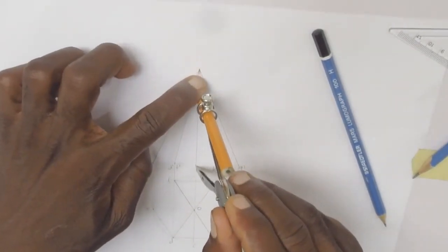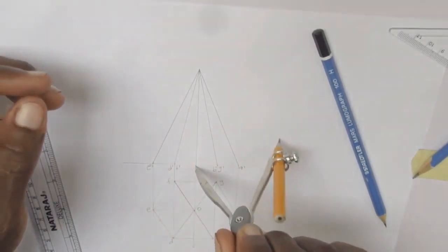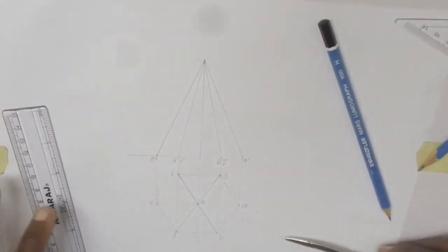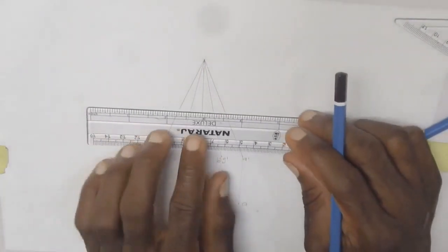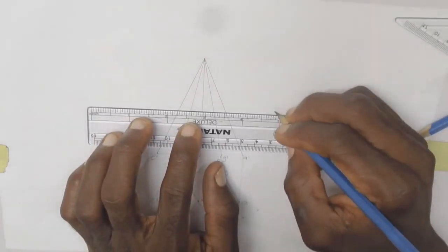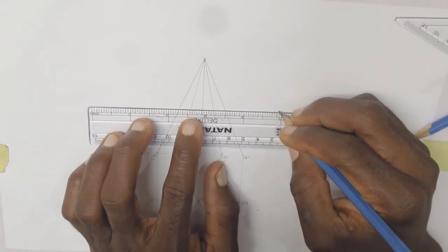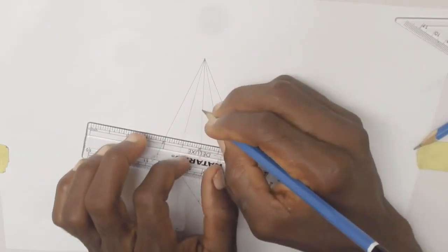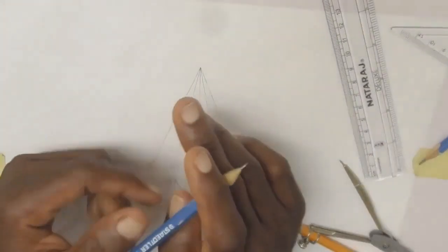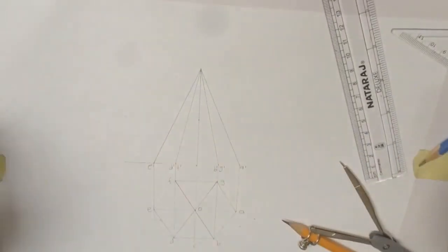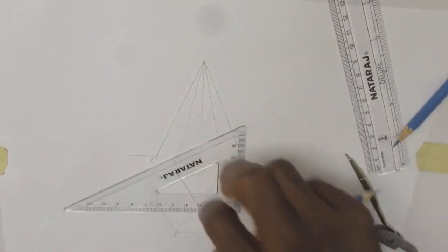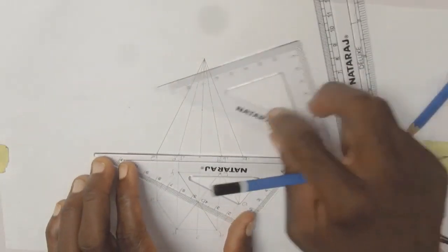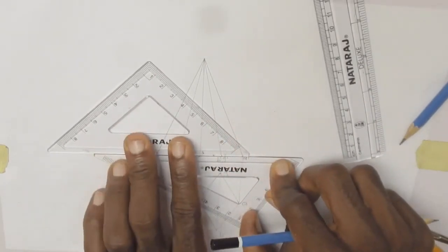So this 75 millimeters, which is the height, is not something that if we divide into two, we're going to have some fraction which we cannot easily read with a ruler. So we need to bisect it. We have to bisect the axis of the pyramid on the front view. So you can just use the normal bisection method and obtain the center point instead of measuring 37.5, which is half of the height. That 0.5 you may not be able to measure accurately on the ruler, so we just do that.